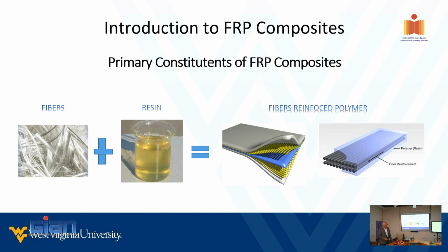So quick question. Especially with respect to GFRP rebars, especially among Indian manufacturers, there's a tendency, it's a very cost-sensitive market, so they tend to put a lot of fillers. Maybe you can sensitize when you talk about it. Sure. I'll talk about it a great deal. While we are talking very briefly about fillers, I want to immediately state that if you go beyond 15-20% of filler by weight in terms of the resin, you are going to degrade the properties.